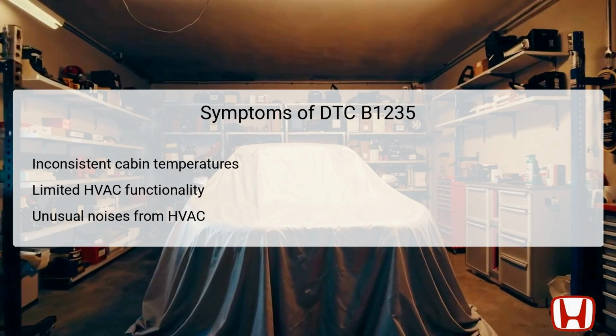settings. Drivers may also hear unusual noises from the HVAC system when the air mix control motor is malfunctioning, or when there are issues with the linkage or door, as these symptoms can directly affect driving comfort and safety. Addressing them promptly is essential for ensuring a pleasant driving experience.